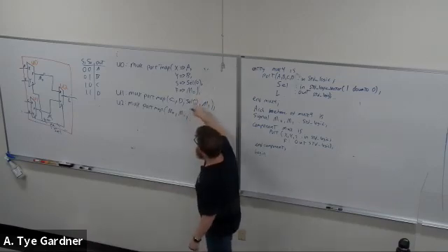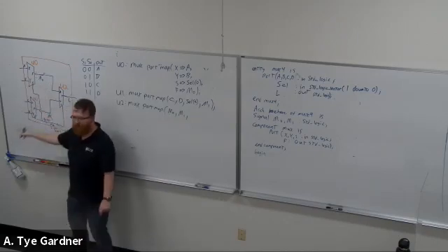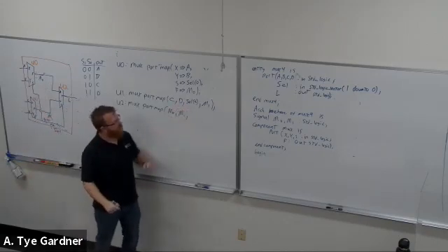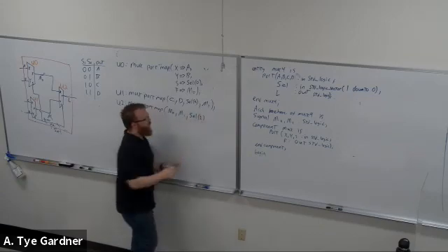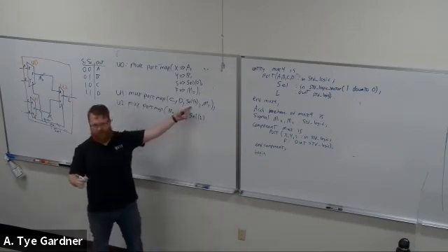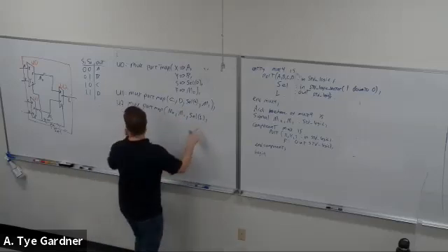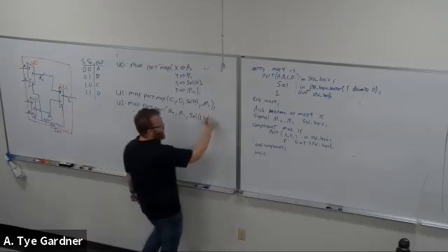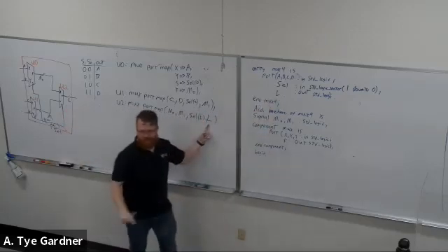Select 0. This is select 0 as well. These first 2 need the same signal. So that was a mistake. That's okay. This one takes select 1. If you make this typo, next time we will teach you how to design simulations to find the problem. And then its final output is L, right? Because I want this guy connected to my output.